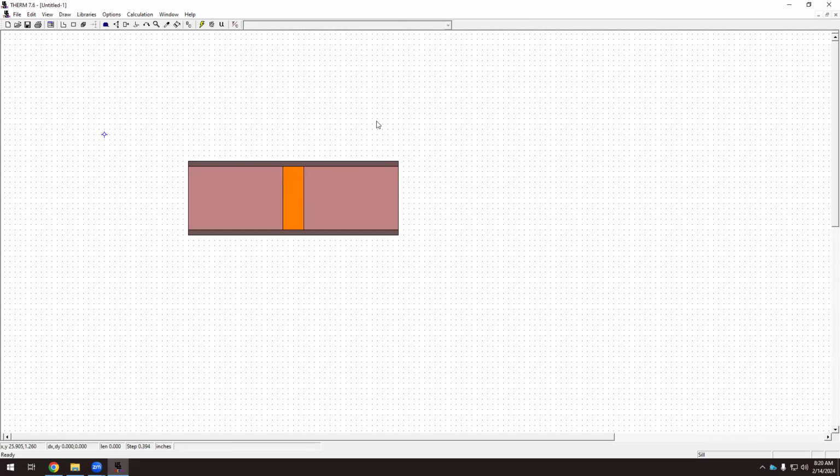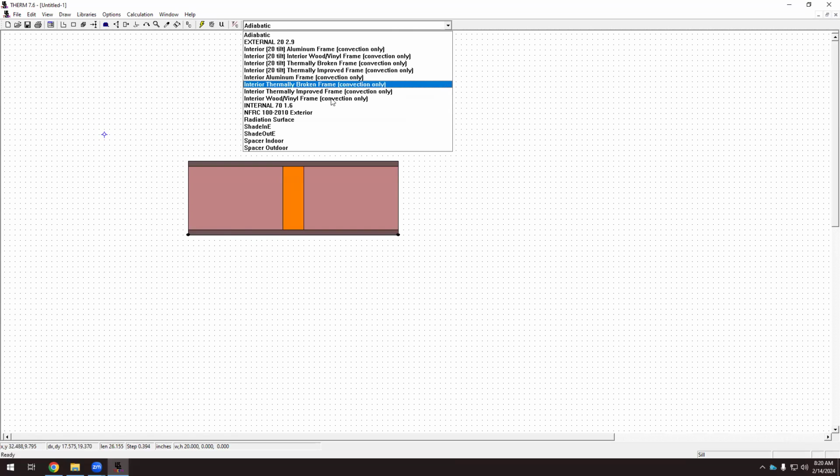So it's a simple detail, but now it's interesting because we can do this with the Excel file. We can analyze a detail that has 2 different materials. We can, but we have to create 2 different tables. So now we need to work with the boundary conditions. Select BC, click here, BC, draw boundary conditions. And now we have to pick the internal one, this one. And if everything works, the boundary condition that we have here, yep, I created this internal